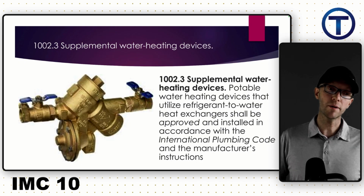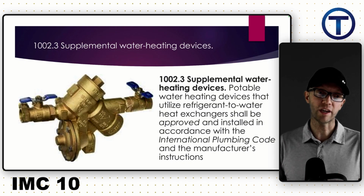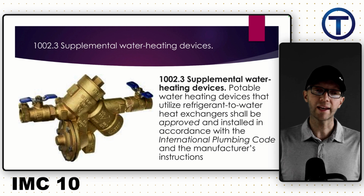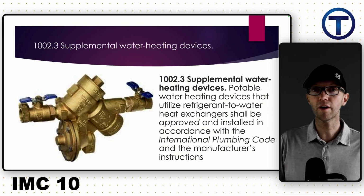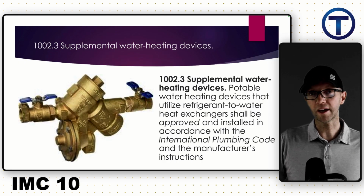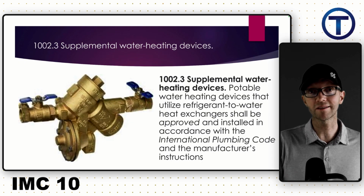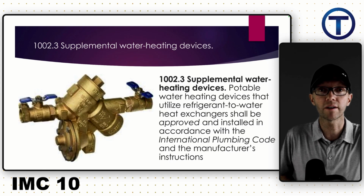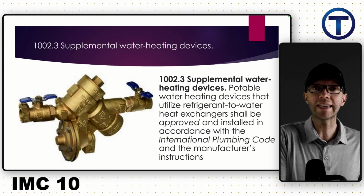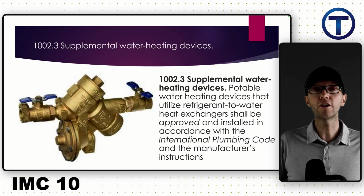This paragraph says potable water heating devices that utilize refrigerant to water heat exchangers shall be approved and installed in accordance with the International Plumbing Code and manufacturer's instructions. So refrigerant to water means if you're going to cool something off using a refrigerant, you have to remove BTUs and put them somewhere else. Wouldn't it be convenient if you could take those BTUs you're pulling heat out of the refrigerator and put those into something that you want to heat, like your water heater? That's the supplemental exchange, and you can do that.